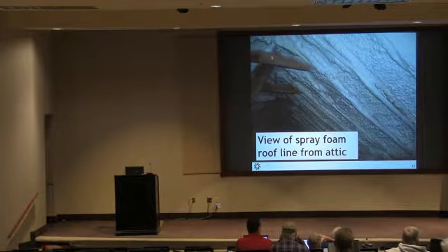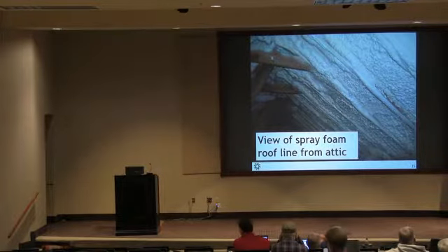Yeah. This eliminates knee walls, which is a big advantage, and it eliminates the problem of trying to use a single-sided air barrier, your ceiling drywall, as your primary air barrier for a product that requires an air barrier, when you know you're going to be penetrating it with all types of holes, and you know you've got the biggest delta T that home is ever going to experience. It's trying to keep it 70 inside, it's 120 in that attic, a 50-degree delta T.